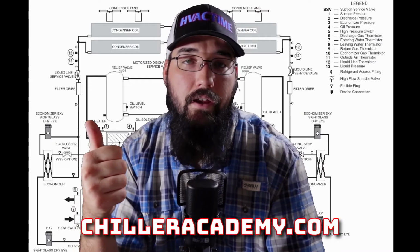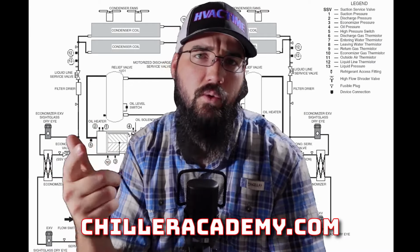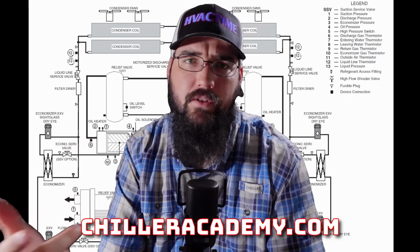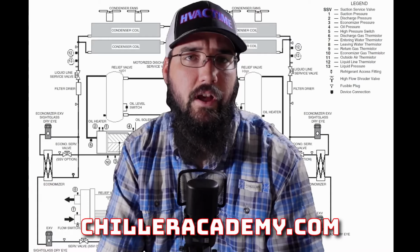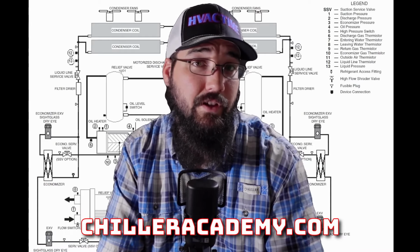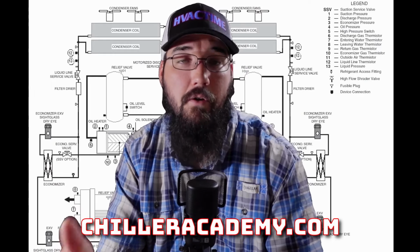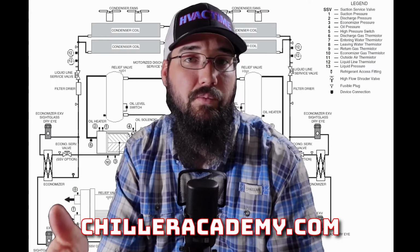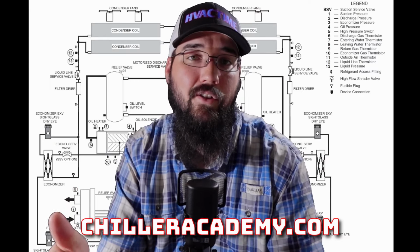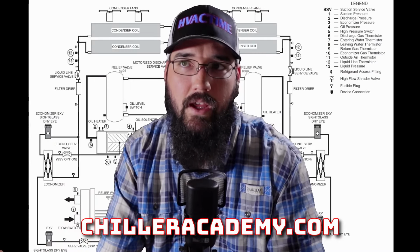You'll have a low pressure limit, a high pressure limit, and a current limit. The low pressure and high pressure limits are just like what we've been discussing. If your evaporator pressure gets down below a certain point, it's going to start limiting you to where it won't allow the compressor to stage up any further because of risk of pulling the suction pressure down. Our main goal is to keep that compressor online and make that chiller produce as much cooling as it possibly can at all times. Now, on the high pressure side, exact same line of thought.